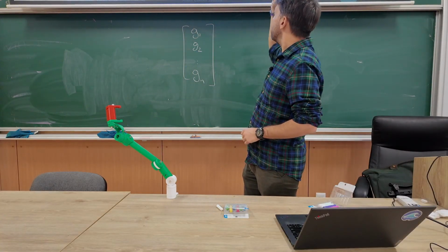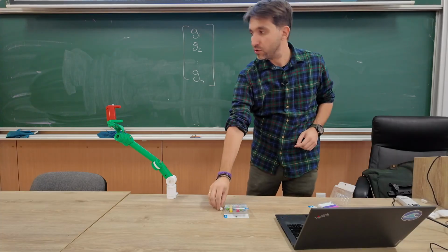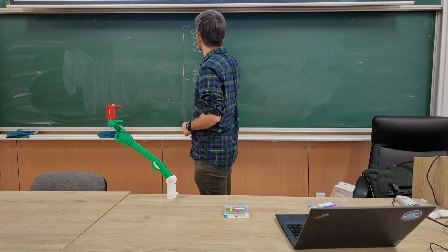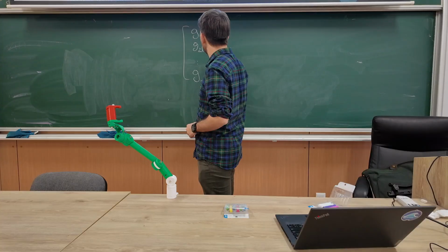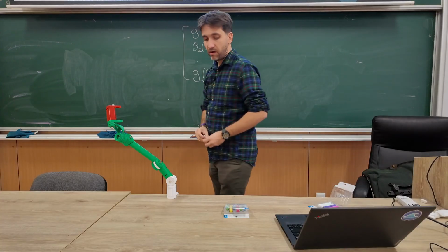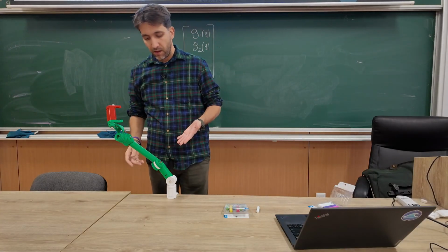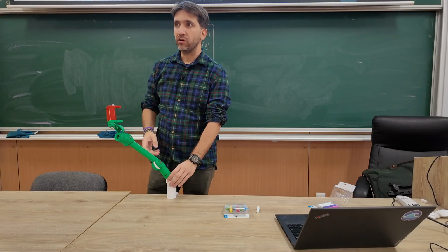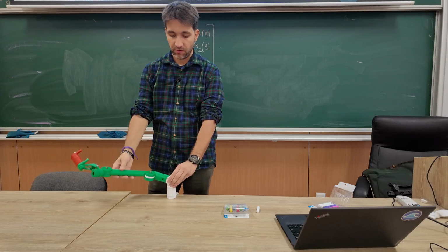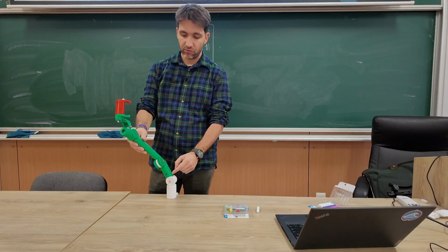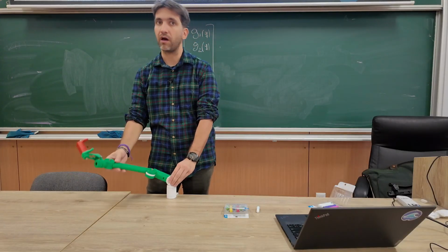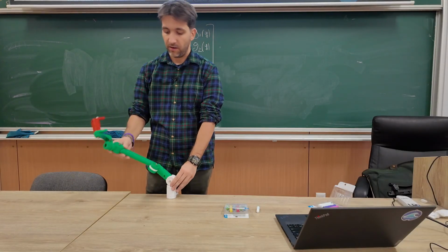And you see also on the slide, and it makes sense, that these are functions of Q. Right? Why is this a function of Q? Because let's take this joint example, right? The torque that it has to counteract has to do with how the robot is positioned, right?